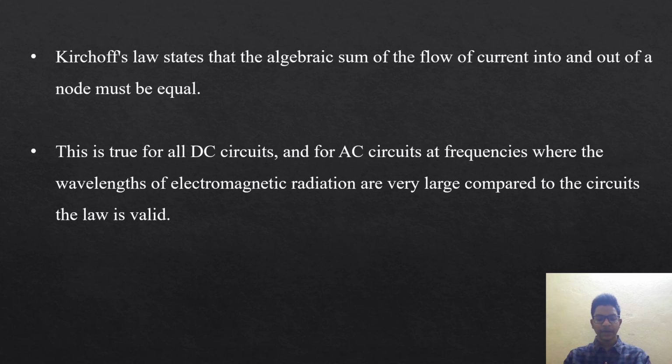These laws can be used in the analysis of practically any electrical circuit, but there are pros and cons to everything. Similarly, Kirchhoff's law also has various limitations and disadvantages. The law assumes that the closed loop has no fluctuating magnetic field in it. Induction of EMF or any electric fields in the circuit is possible, and this will eventually cause the current and voltage rules to fail. High frequency circuits are also affected. Another issue is that only if electric charge is constant inside the circuit is KCL valid and applicable.